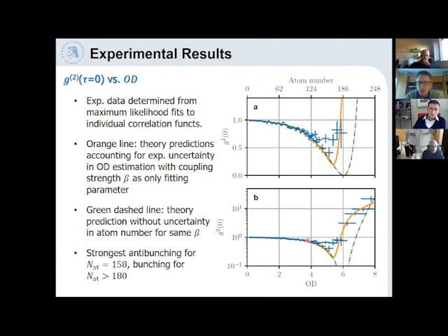So when stretching the fiber while brushing with the flame over it, you can calculate what comes out. Our modeling of this process gives us an a priori precision of the final fiber diameter which is better than plus minus 5%.